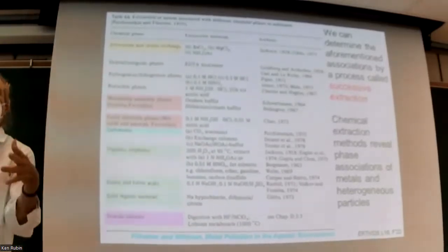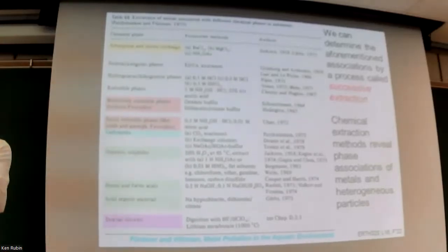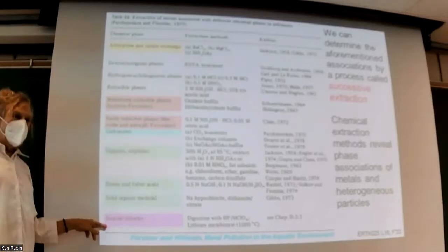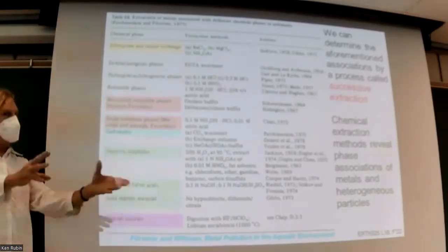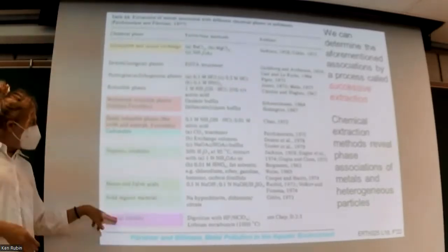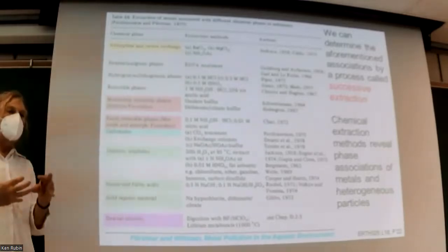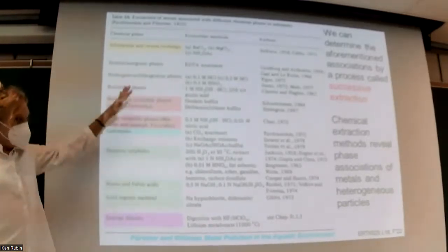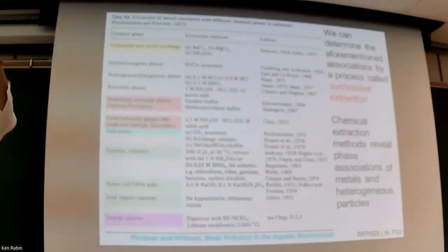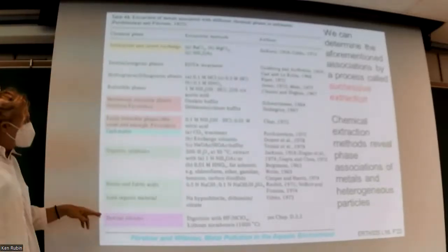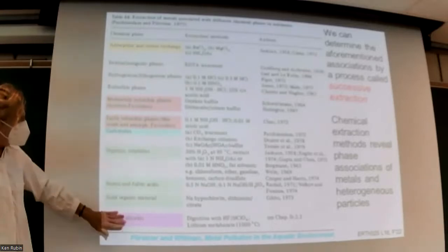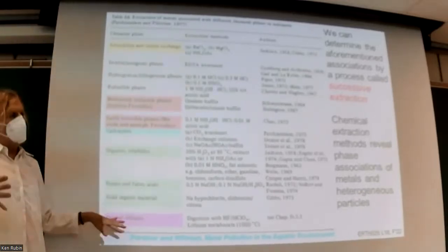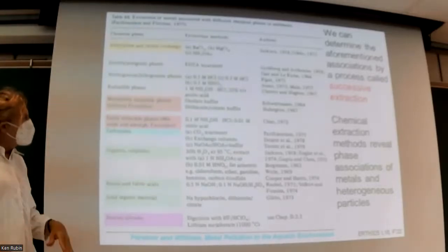The stuff that is, for us, like the particles of the salt rock that are coming down the watershed. They're the hardest to dissolve. The stuff that's in them tends to stay in them. And these primary mineral phases tend to not stick very much stuff onto their surface. They're just the extra stuff that flows down the river and contributes to sedimentation and perhaps the process of flocculation and all that stuff. So you've often seen that a lot of states don't even bother with this, right? Because this stuff doesn't really impact the water quality per se. It's just going to settle out.